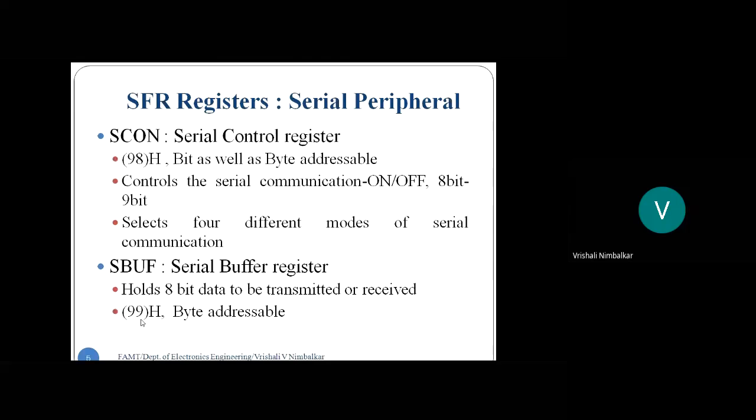Whatever arrives on RxD will be stored in one SBUF register, the one which is activated by the read control signal. If the microcontroller takes in any data, that is a read operation. So RxD data will be saved in the SBUF register controlled by the read control signal.